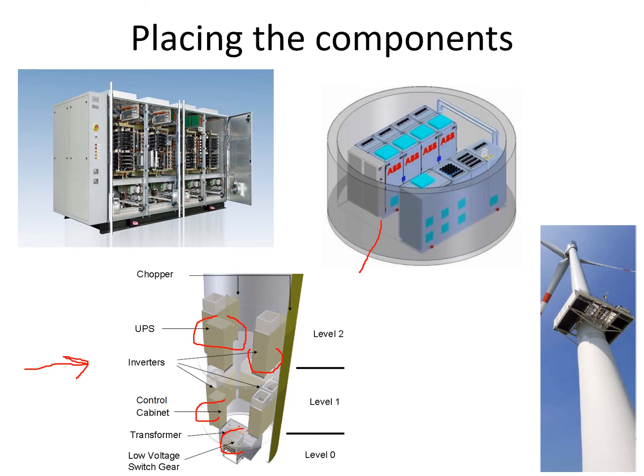This picture here is showing how frequency converters can be placed inside the tower, so that we have a passage between them for the staff, and we have them connected to each other from top. Sometimes transformers or electronics can be put on the tower of the wind turbine instead of pushing them into the tower. This is quite an interesting design topic: putting the common components together so they fit the space and there's a good connection electrically between them, and so on.